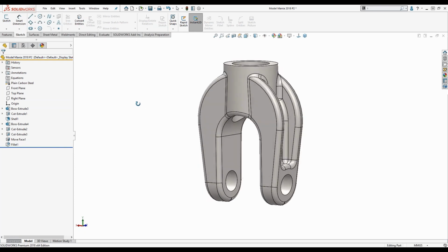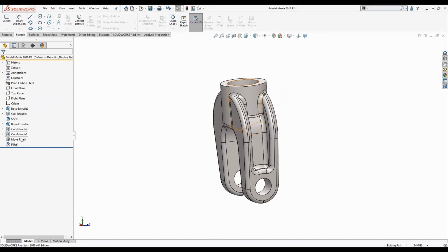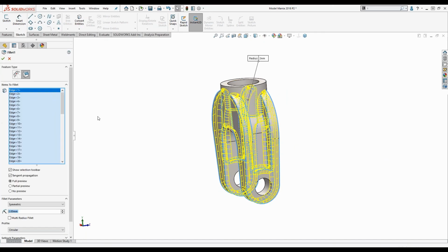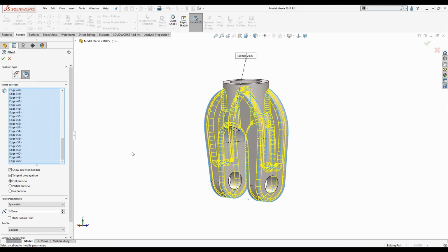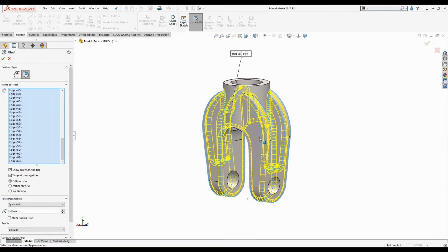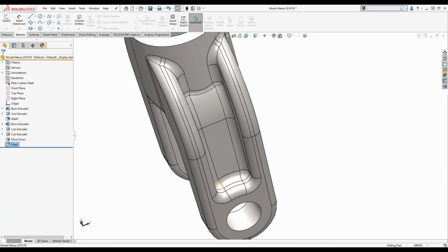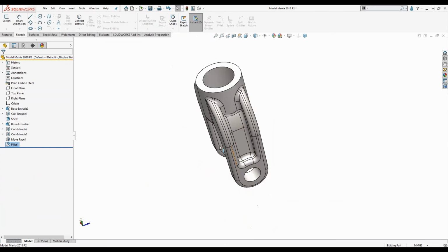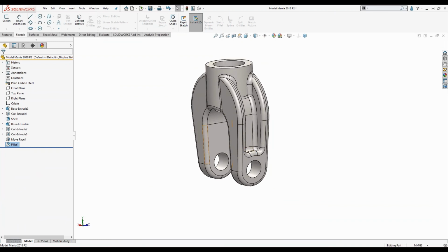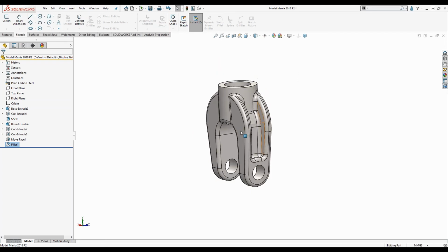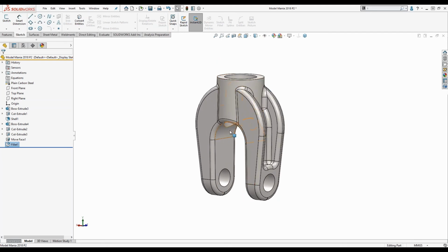And then I utilized that selection manager again. This was quite tricky with the selection manager because there are a lot of fillets you need to pick up on this one. There are 62 fillet edges to pick up. So you really have to make sure that when you're going through the selection manager, you're picking up the correct edges. In this case, these inner ones were extremely challenging because it had to look exactly like this. And I believe the selection manager wasn't picking up every single edge here, so you actually had to go in there and select a few edges and make sure you got everything. It also wanted to continually pick up these circle edges, which I did not want. So that's the completed phase 2, right?